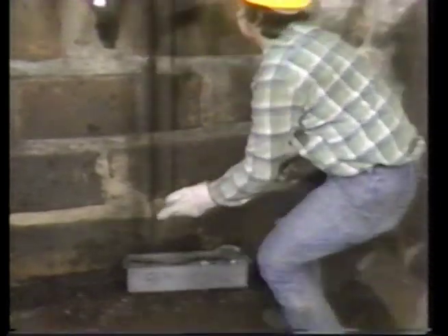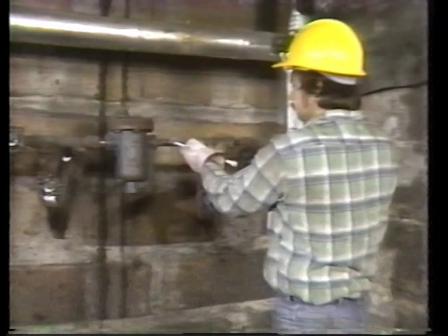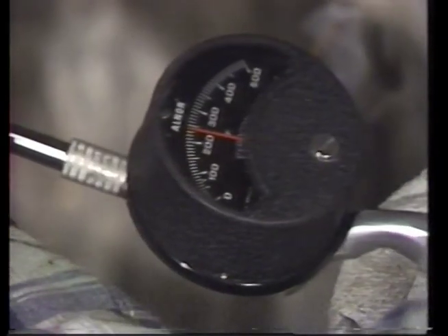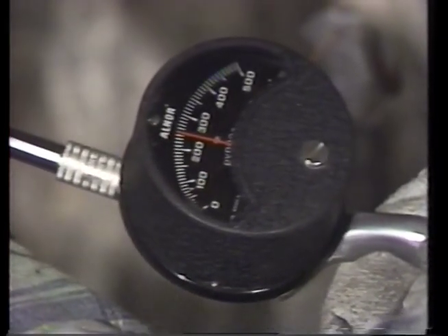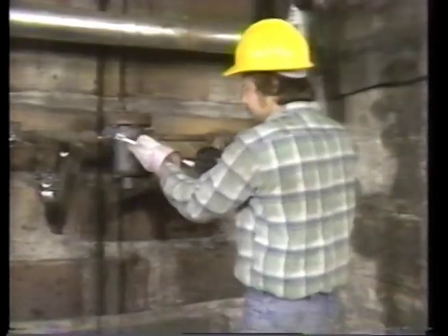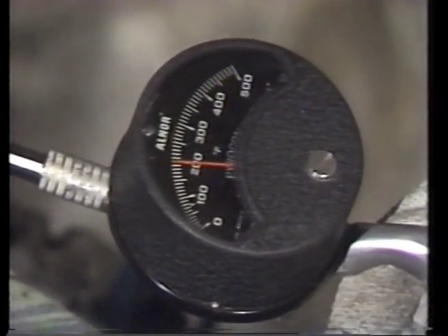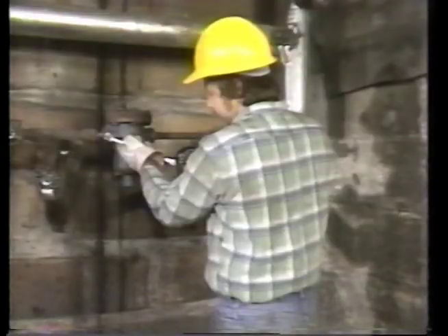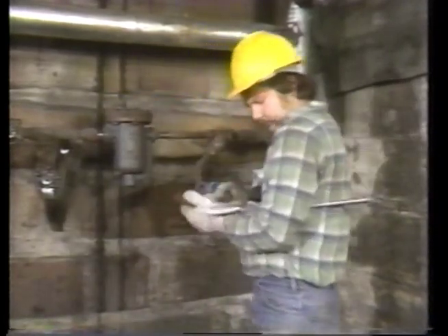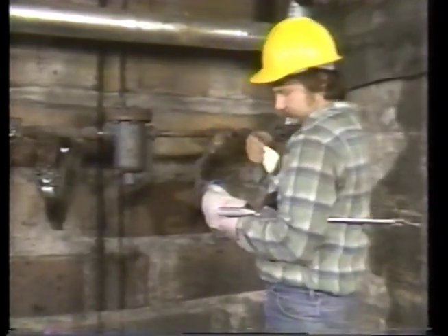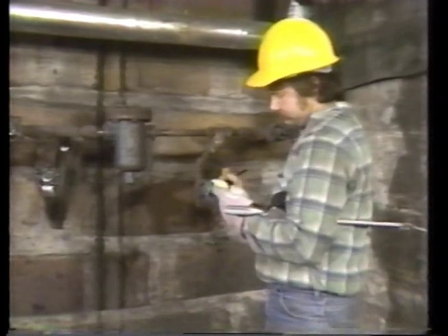After you clean the areas, go ahead and take a temperature reading at the trap inlet. Be sure to hold the pyrometer in place long enough to allow it to respond properly. Repeat this procedure at the trap outlet. When you've taken both measurements, write them down on a piece of paper. Remember that we're comparing the temperature we obtain with the allowable temperature range from the chart in the text.